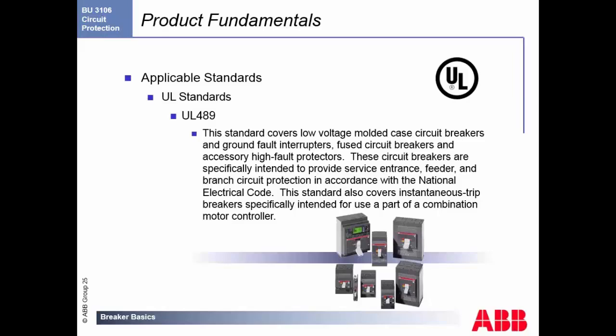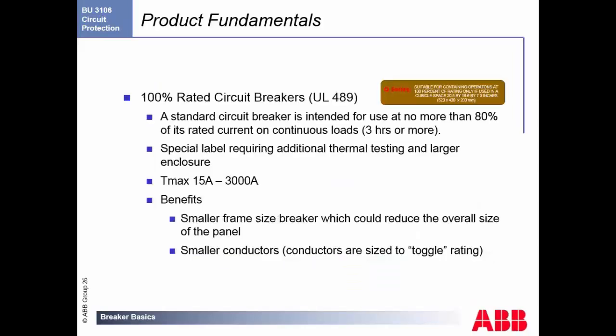It's in accordance with the NEC, the National Electrical Code, and it covers instantaneous trip breakers. Basically, when you're using anything with power and you need a breaker in there, the motor controls always have to have breakers by the NEC. The MCCBs are what you're going to be using in your switchgear. We have 100% rated circuit breakers, UL 489.